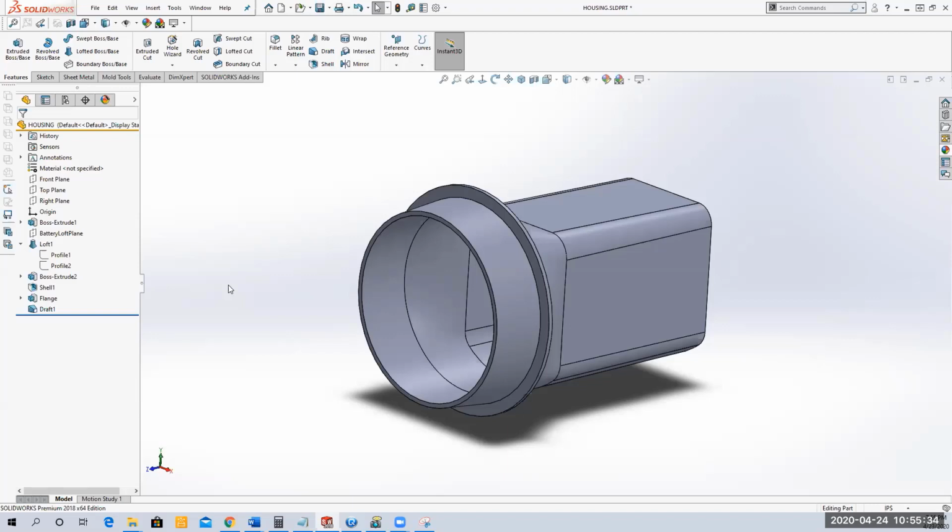But before we do that, we're going to create the thread profile, the thread path. Now remember, when we created the thread in the lens cap, we had to bring in the thread a little bit so it wouldn't strip. So we had to add a plane. Do you remember doing that last week? So if you look on the bottom of page 6-43, we have a new thread plane. So we have to create a thread plane, and it's going to go in 1/8 of an inch.